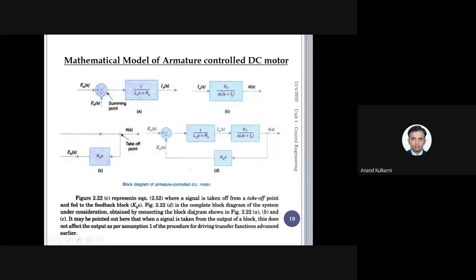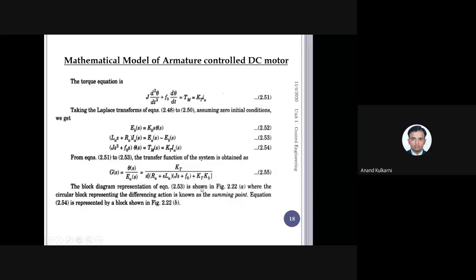Coming to that, you can write down the equation for the rotor now. So this rotor has polar moment of inertia J. So the inertia component plus the damping component is equal to the torque. So for a rotor, the supply is torque, that is Kt into Ia, Tm, and due to that the drop of torque takes place due to J into d square theta by dt square, that is J into alpha, the angular acceleration.